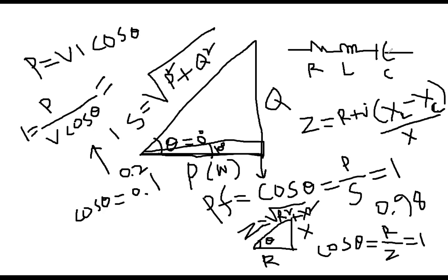Now, what is the impact? Come back here. Look at the current in this circuit. When 10 amperes was flowing, just an example, you will get I squared R power loss, or I squared XL, or I squared XC. On the other hand, if the current value is much lower, your loss will be much lower. And your voltage drop, from this point to this point: if you have higher current, you will have a higher voltage drop, so you will get much lower voltage here.